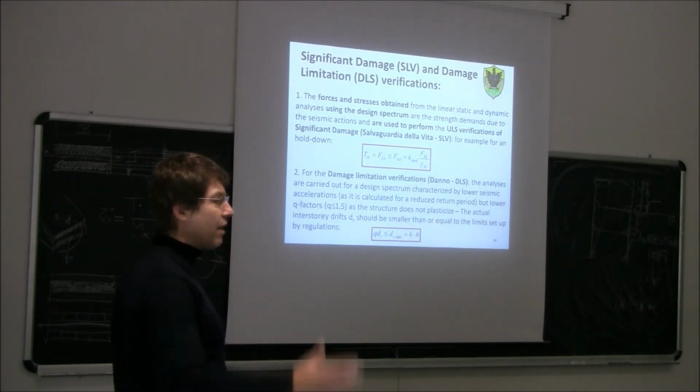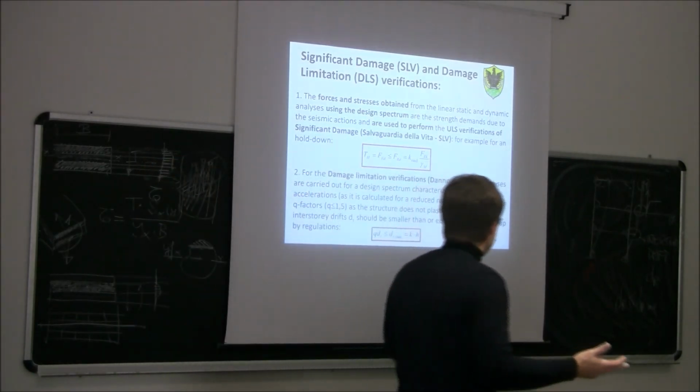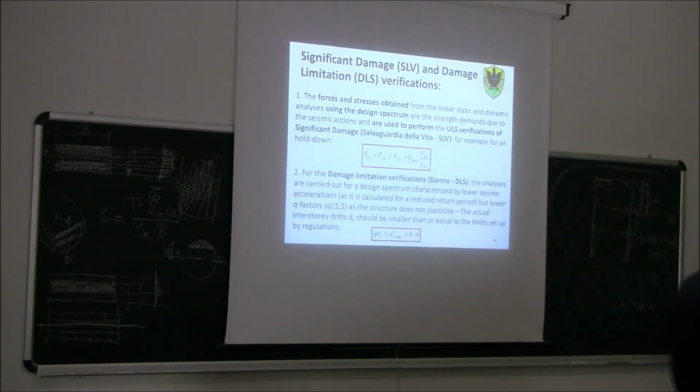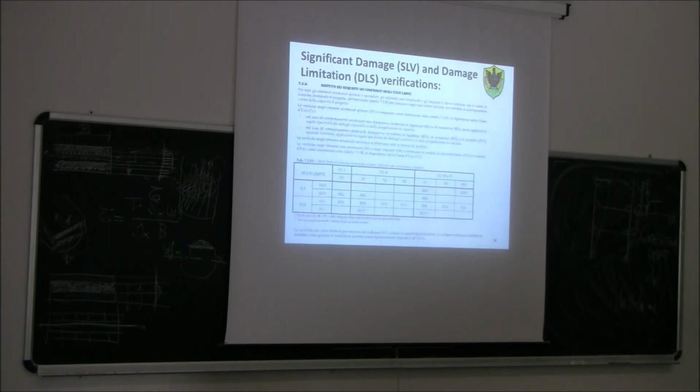For example, if you have a partition, internal non-structural partition, the damage is limited by the interstory drift, because the possible damage on the partition depends on the interstory drift. If the interstory drift is too big, this partition tends to be subjected to some relative displacement, and then we can have some formation of cracks or other things. So, for example,